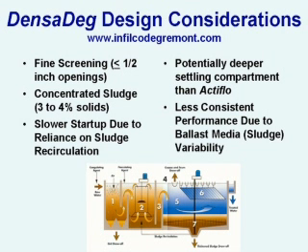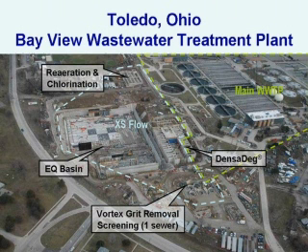Grit removal was required. The sludge characteristics from ActiFlo are relatively thin, and the volume of flow that needs to be recirculated is about 2 to 3% of the influent flow. ActiFlo also uses an engineered media for ballast, and that requires that to be maintained during the use of this type of technology. DensaDeg also requires screening, but half-inch screening openings as opposed to the quarter-inch for ActiFlo. It produces a concentrated sludge, 3 to 4% solids, which has less solids handling requirement than was anticipated with the